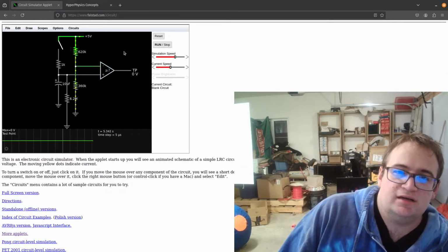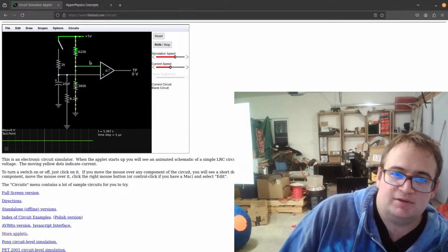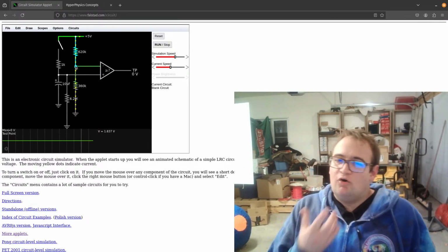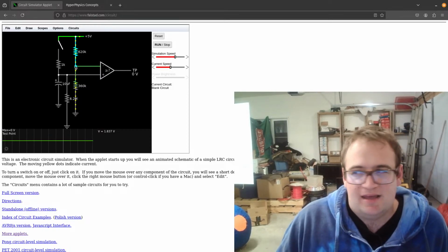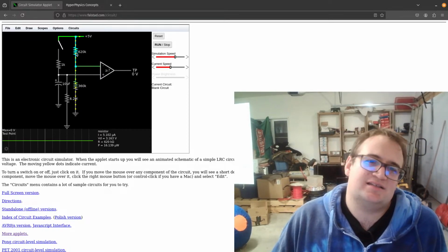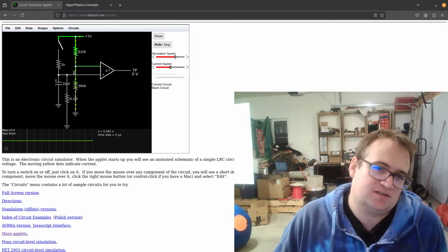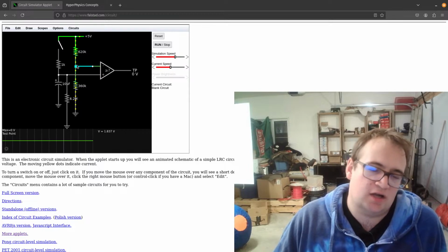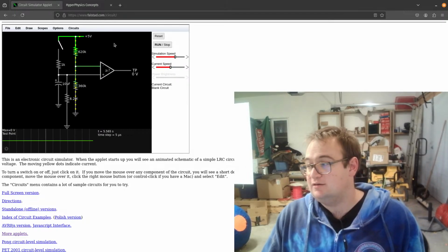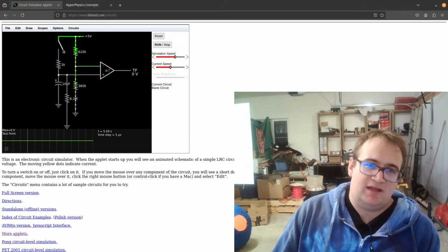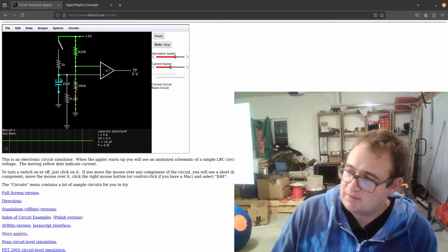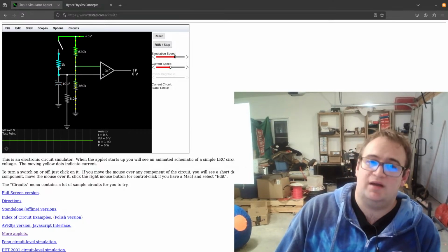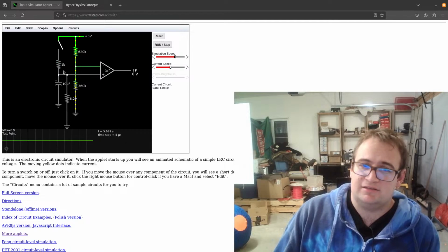Let's just run it. So you see right now nothing's happening. It's 1.8 volts, so I was wrong there. Oh yeah, no, I was right, but I always get that mixed up. Because this will burn up 3.2 volts. That means there's only 1.8 volts left. So my logic was right, but my math was wrong. But now when I flick this, this capacitor, if I'm right, will charge to 5 volts fairly quickly, because this is only a 1K resistor.